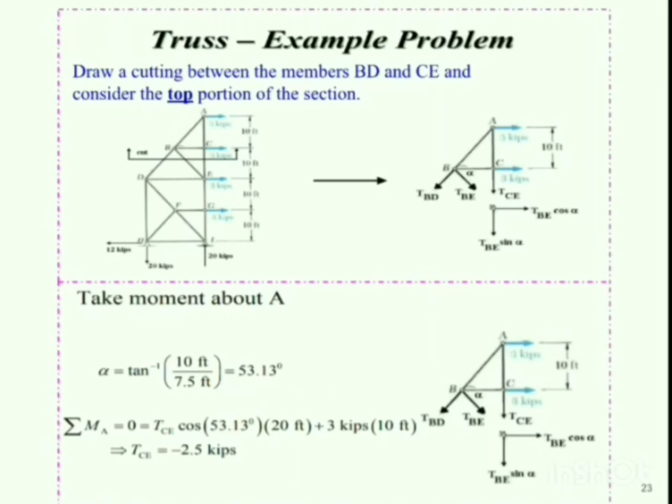But again, I'm repeating that we shouldn't change the direction of the forces that we have shown in the free body diagram. We need to keep them as they are. We need to carry the negative sign with these member forces ahead if required in the equation.